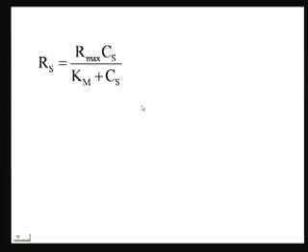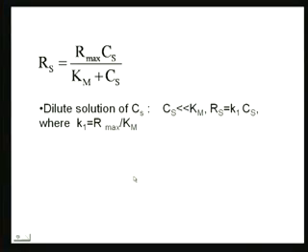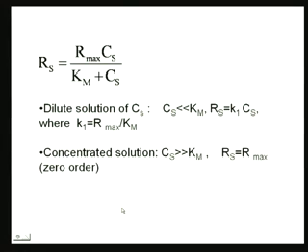So what we do is what we did before, which was to look at the two extreme ends of the problem, the two asymptotes: a very small value of Cs, where the system follows first order kinetics, and a very large value of Cs, where the system follows zeroth order kinetics. So what's the advantage? The real order of the system is a fractional order between 0 and 1, and if you can find the two bounds of the solution, your real solution is going to be bounded by these two solutions. So if we can find the two bounds, between the zeroth order and the first order, we are sort of in business.